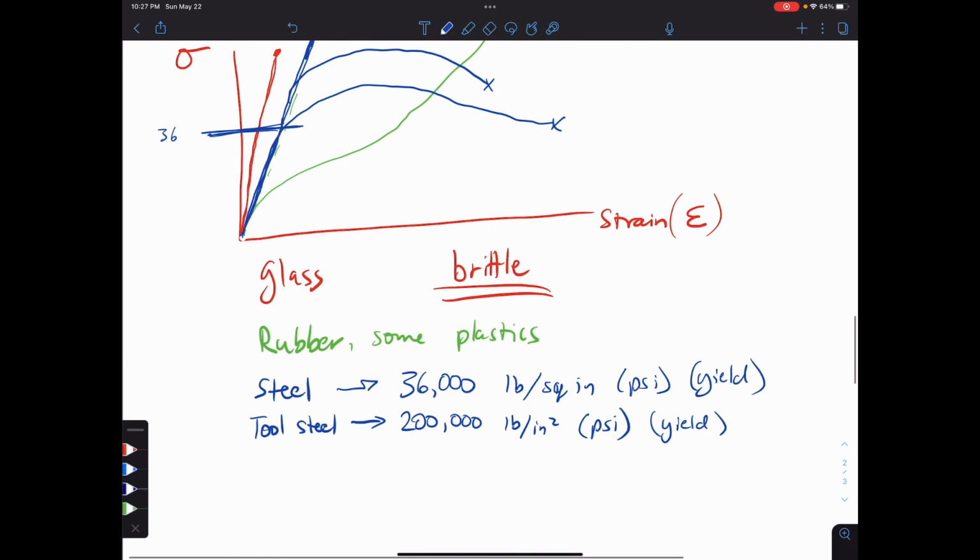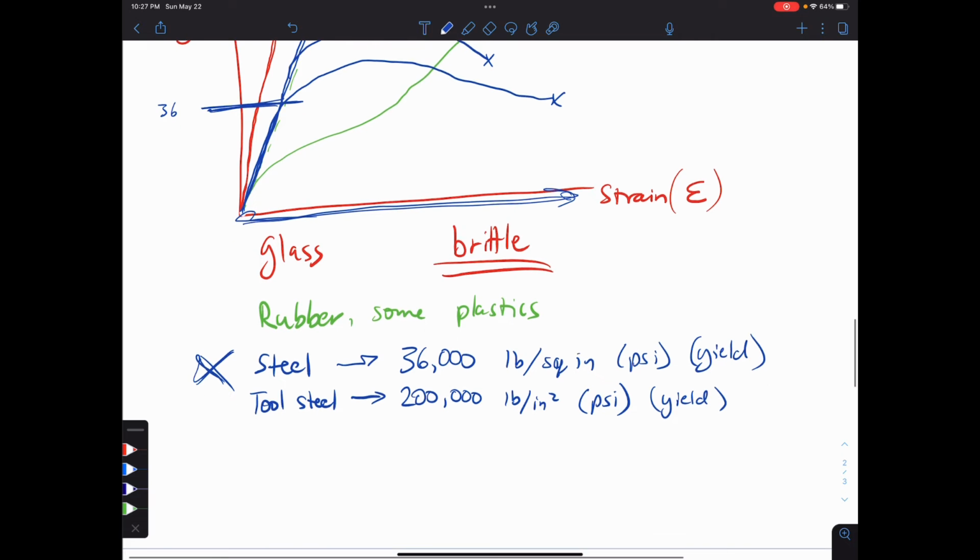You can imagine that this steel here, with a long plastic strain region, is pretty helpful with just kind of steel that needs to be able to be pounded around and shaped into something, steel that doesn't have to be particularly strong, etc. Steel that needs to be able to tolerate being bent without breaking.